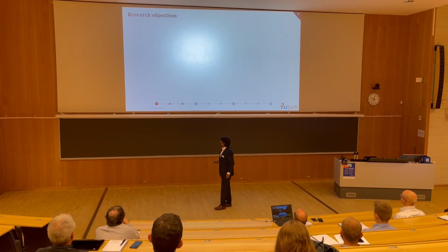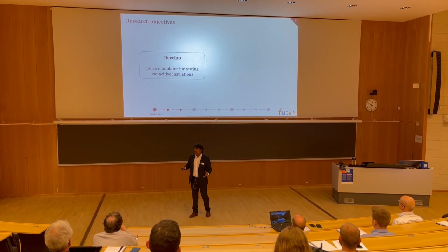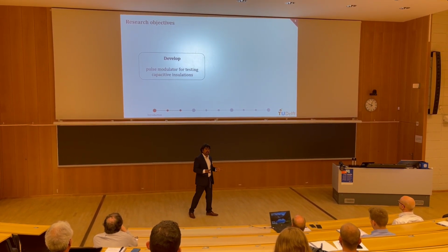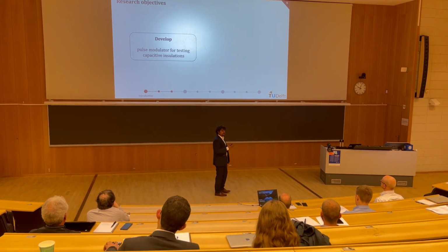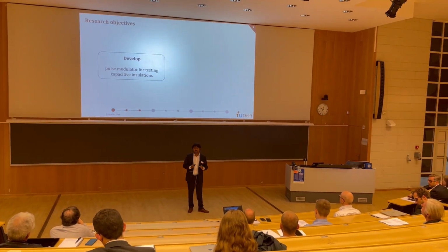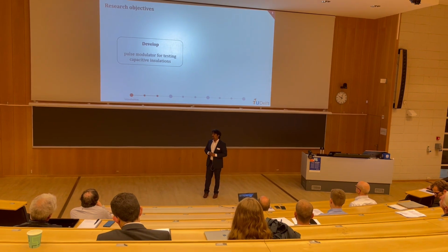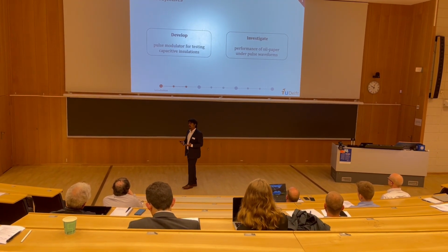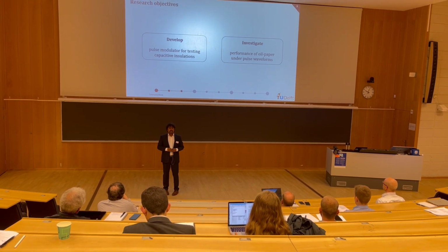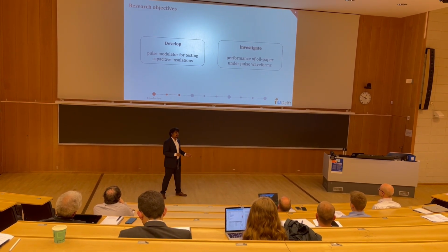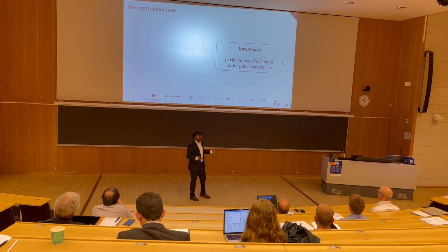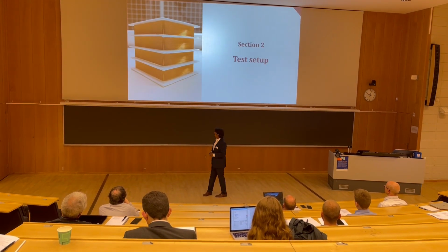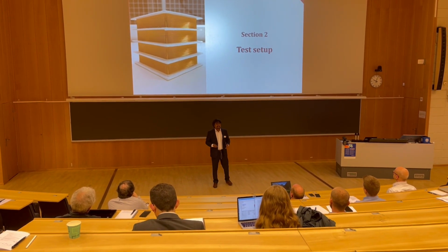So my master thesis was quite simple. The first idea was to develop a pulse modulator that can produce these kinds of pulses across capacitive samples. This has not been done before. The second half was to investigate the performance of oil paper under these pulse stresses. The paper we submitted for this conference, however, is only about the second one, so I will try to focus more on that. Quickly talking about the test setup.